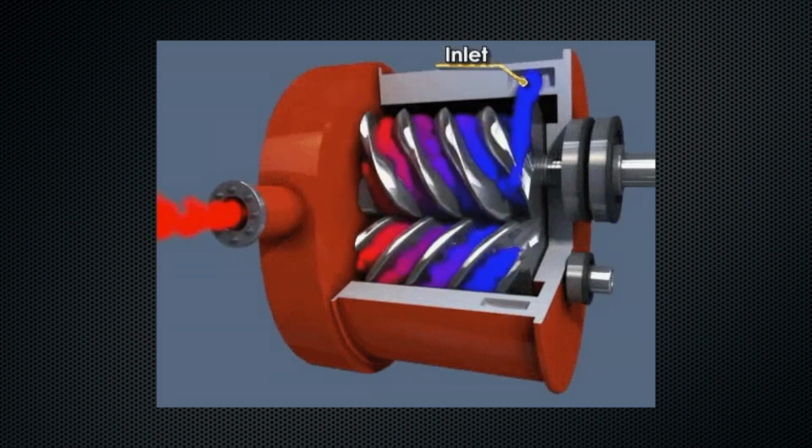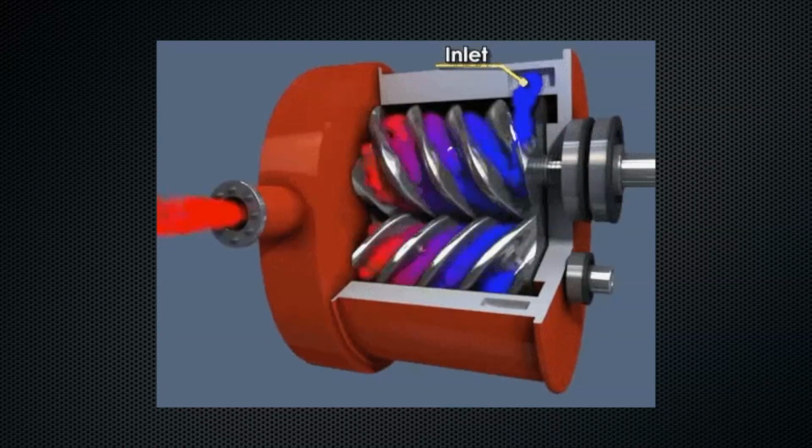People like them because the air is delivered smoothly and quietly. No pulsation like the recip. But there is a higher waste of energy when you unload it. What are you going to do? You can either bypass with high pressure air and recirculate it around itself, or just operate against dead head. Either one of these cases is a waste of money.